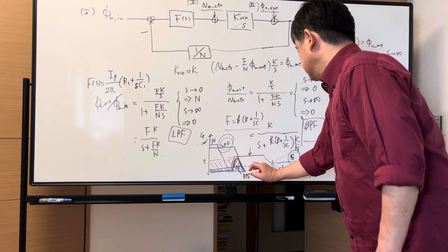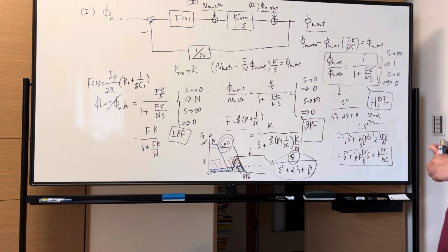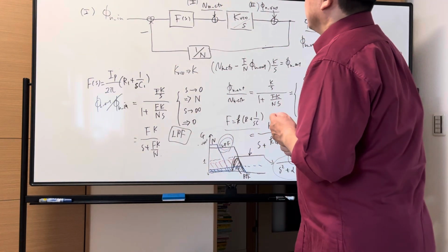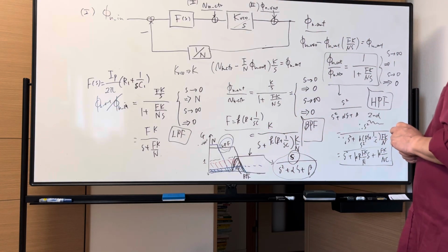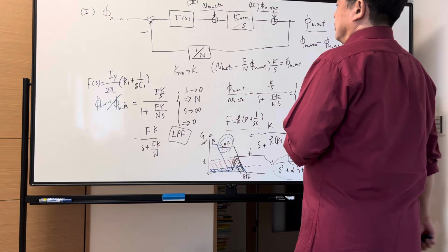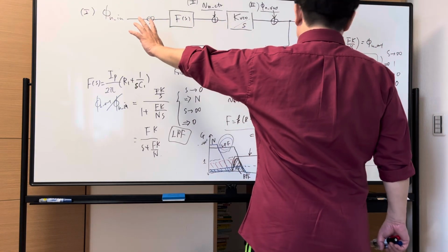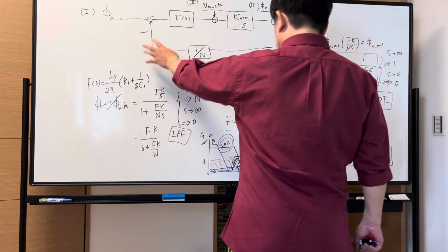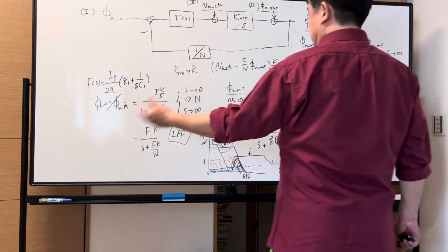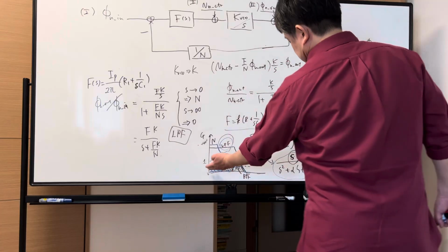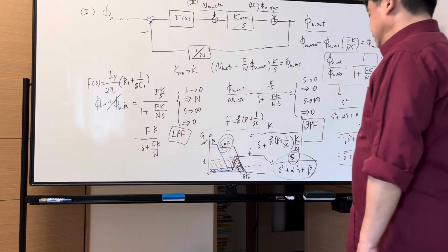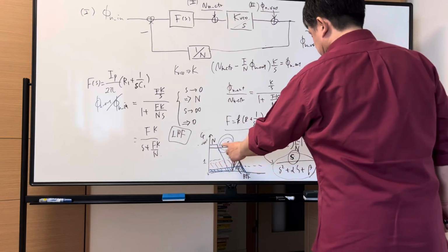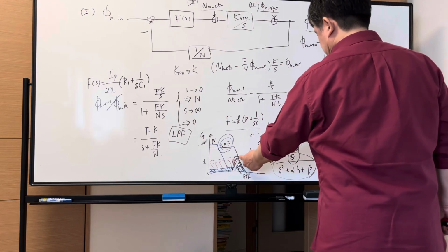But if the input noise remains larger, we couldn't. It remained like that. So if input phase noise of the clock and systematic or deterministic noise from the voltage source, power line is sufficiently suppressed by decoupling, and the divider and phase detector generate small phase noise, like this blue line, it's good with this loop bandwidth of the PLL, low pass filter configuration, high pass filter configuration, band pass filter configuration.